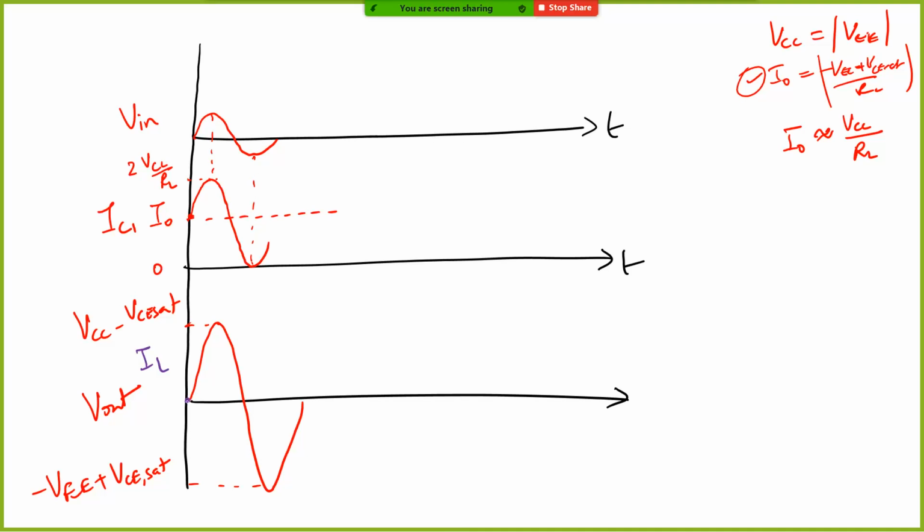Yeah, and it is going to reach, let me say, IL max, right? IL max being VCC by RL, and this is minus VCC by RL. IL is going to be centered at 0, but the quiescent current which is flowing through your transistor Q1, there is going to be always I naught flowing even in the absence of signal. So let us compute what is called efficiency.